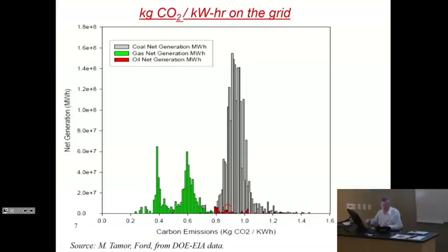First of all, because they're coal-fired, and second, because they're not that efficient. We have a lot of plants that are quite inefficient. Typically, these things are 80 or 100 years old, or so, well, 100 I don't know, but 80 years old plus. The more modern plants now burn gas, natural gas, and they come, as you can see here, in 2 generations. Some that emit 0.6, some that emit 0.4 kilogram of CO2 per kilowatt hour produced. And these are, of course, the more modern plants.